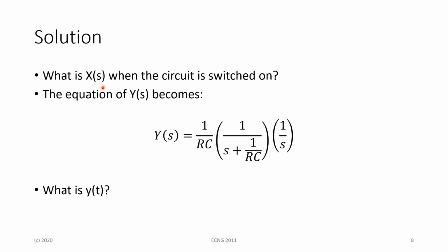The step response is basically when the circuit is switched on, because it goes from 0 to some predetermined value, which in this case could be 1 for our example here. And if you look for the step response in the Laplace table, you see that the step response, being that immediate change in time, is characterized as 1 on s, where the 1 here maps the magnitude. So if we had a step that went from 0 to 12, the Laplace transform for that is going to be 12 on s.